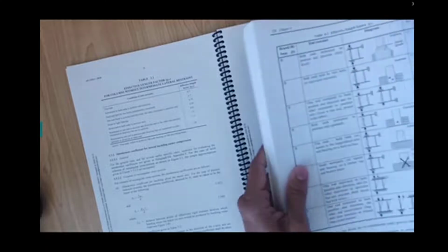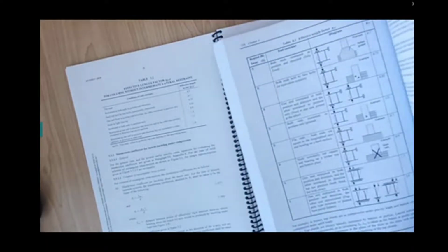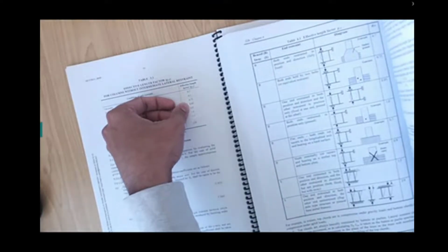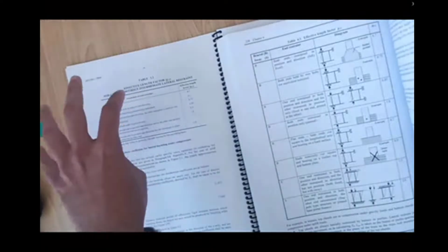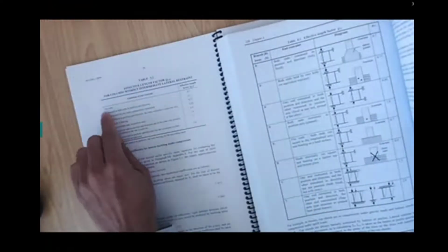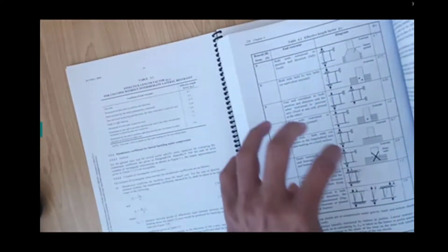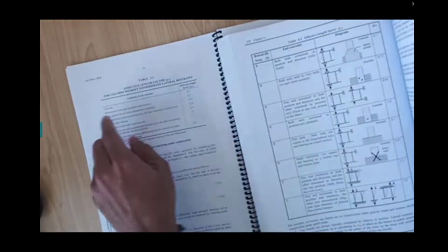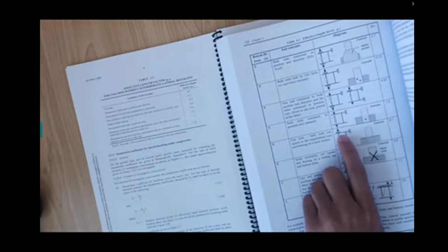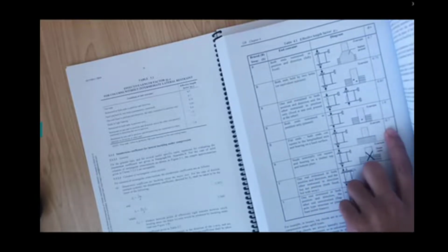So we keep in mind that we're going to have a construction, or we can have a column end, in a way that we will keep these numbers as small as possible. So this is a flat end. This is the physical meaning of those tables as well. I hope you understand. Flat end is a part of brace columns, and flat end has a factor 0.7. This is the picture that I'm just showing you. That is a flat end and it's 0.7.